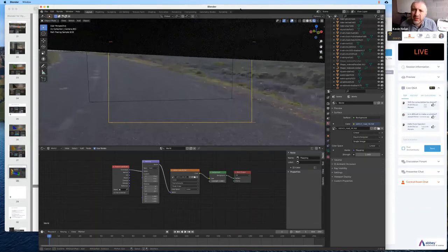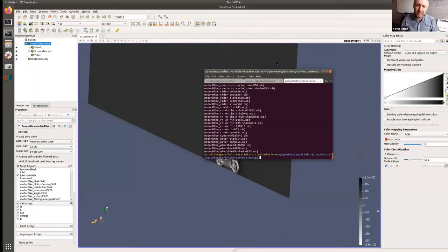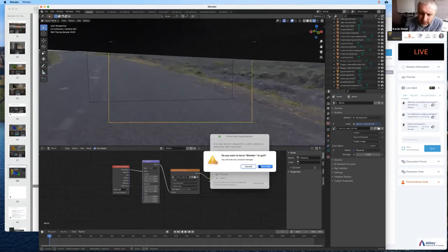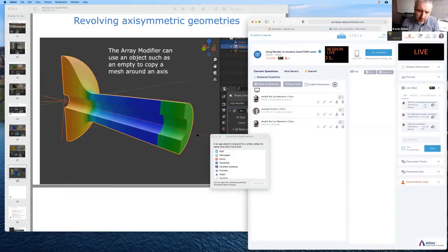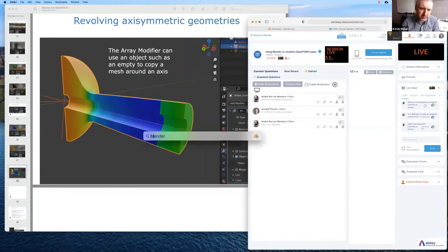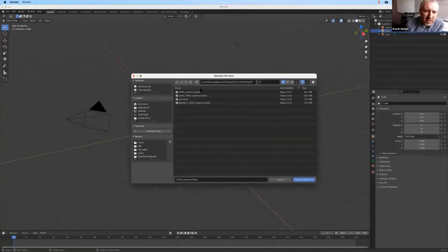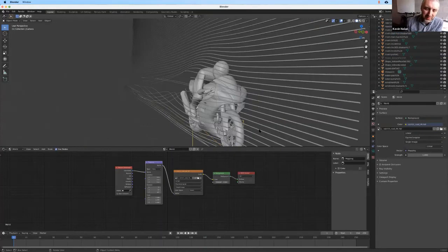Okay, we have a software freeze here. So occasionally Blender will freeze. It's generally quite stable, I find, but occasionally it can happen. If the worst does happen, you can go back into Blender, and it has an auto recovery option. So you just go to File, Recover, Last Session or Auto Save. You'll find our most recent version was saved today, just a minute ago. So we've recovered quite nicely. And I need to fix my cameras.